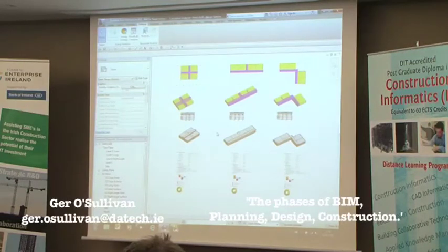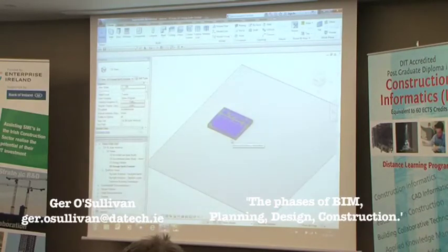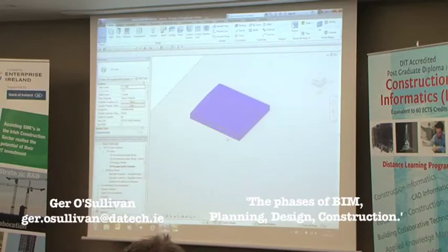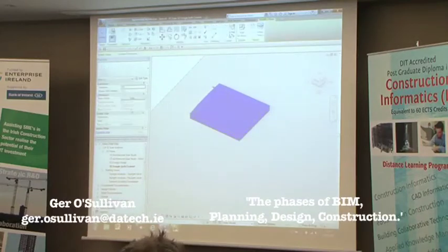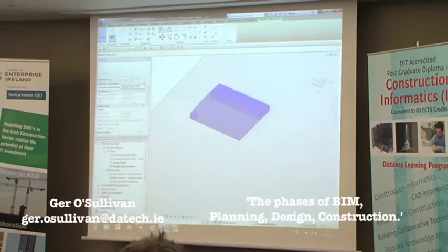You can then start to look more into the design side of the building itself. So I'm going to close this file down and open up a more fully designed building. But again, we will start off at the conceptual stage. This is another mass model, for a supermarket that we're looking at. And again, the areas are embedded in there, so we have zones for the retail area. If I select the overall building, I'm now getting what you saw on the schedule: gross areas, surface areas, volumes. We can even take it down to the zones, and now we're getting our areas again.